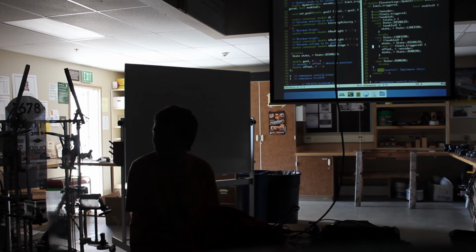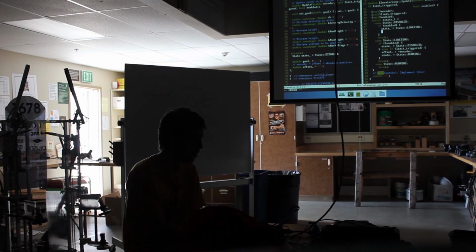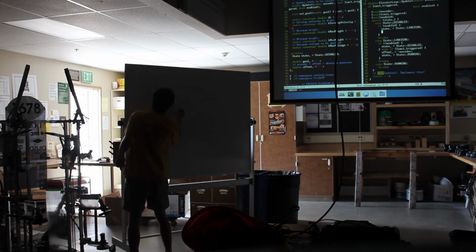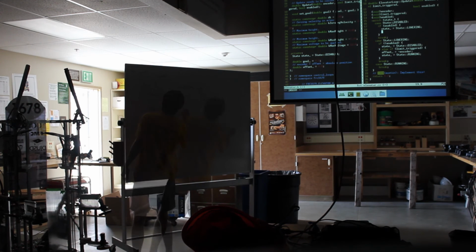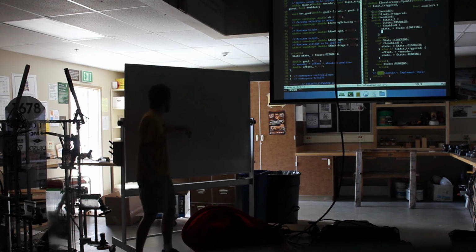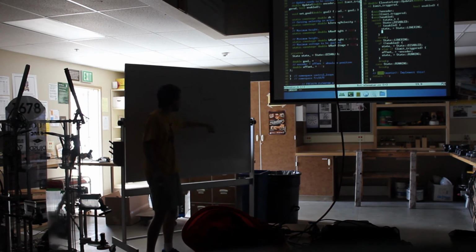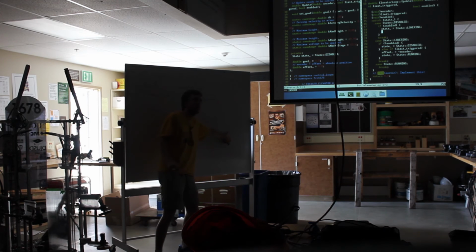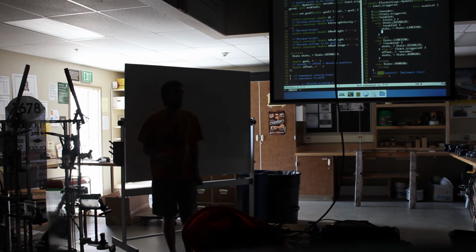So that's going to start in the if you're not running. Yep. So what do we do here? Well, we need to set the goal for the control loop, right? We have a goal coming in. This goes into our state machine. So we have our goal, it comes into the state machine, and then it produces a real goal, which it tells the control loop to go to, and then we send that out. That gives a voltage, which we then send to the hardware.